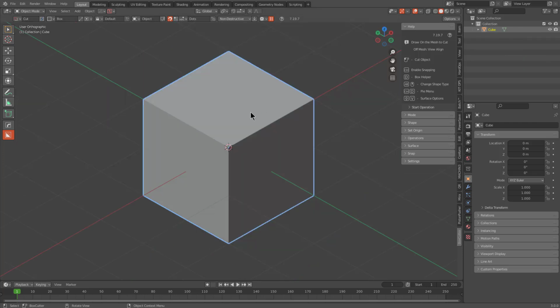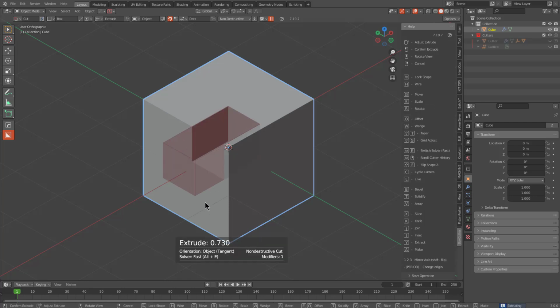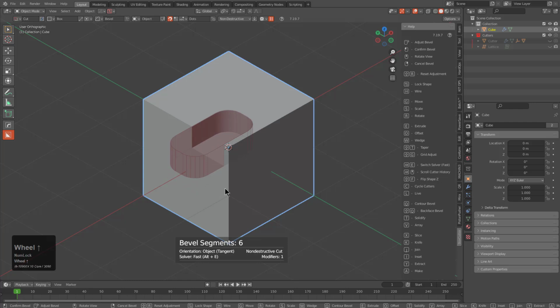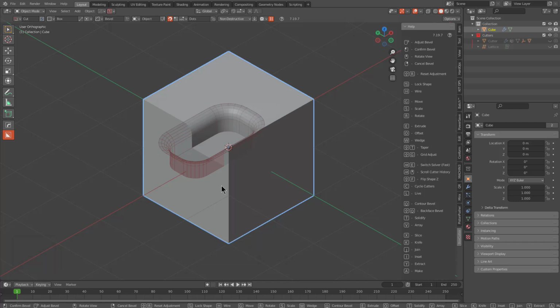In addition to the previous aspects we discussed, there's also reverse bevel. So if we draw a box, we can extrude, we could press B to bevel, we could press Q in order to Q bevel. And from here, we could also press Shift F to basically flip the shape and give us a reverse bevel. Alternatively, you could also do this from the helper.